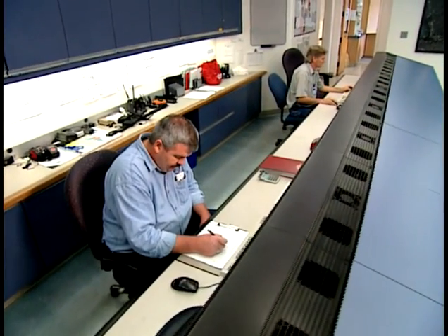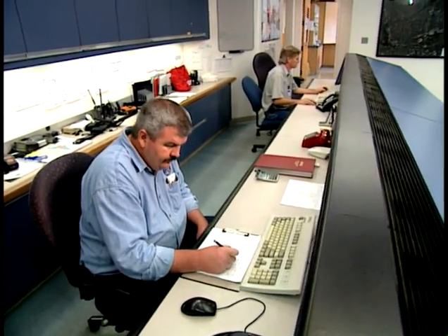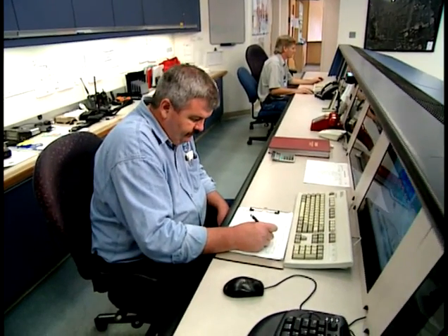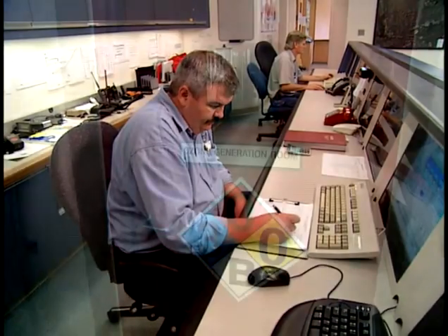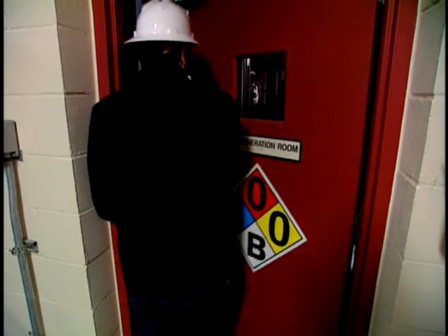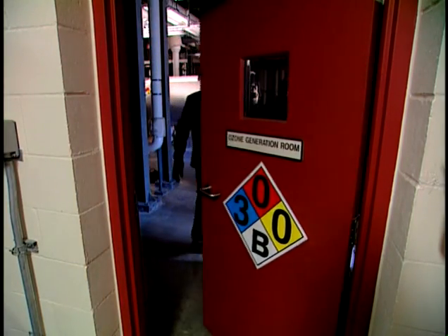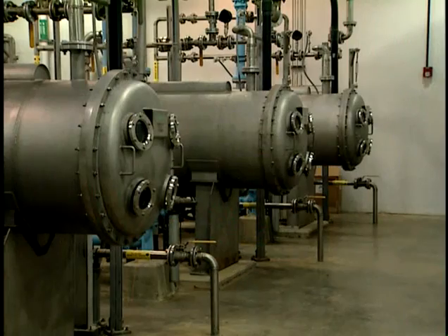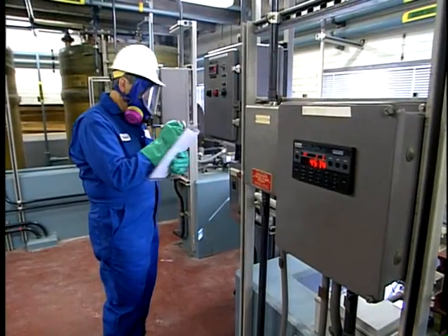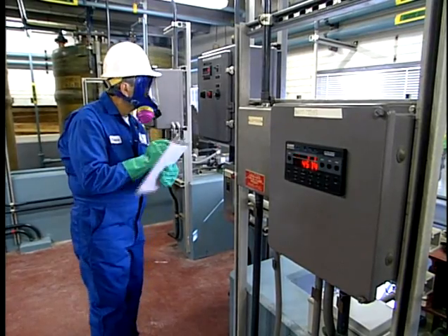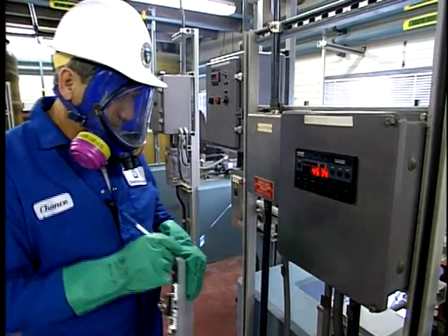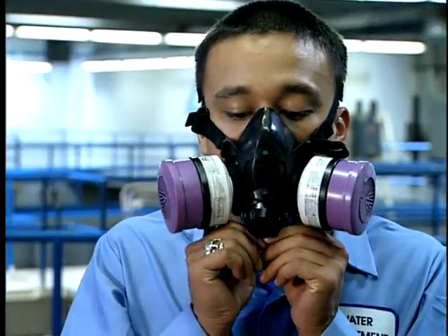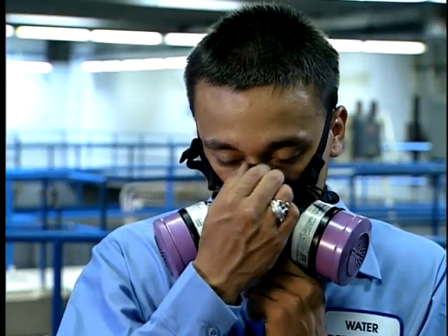Operating limits must be established with consequences of deviation and steps required to correct or avoid deviation. Employees need to be aware of all safety and health considerations of each operation, such as the properties and hazards presented by chemicals used in the process, and precautions necessary to prevent exposure, including engineering and administrative controls and appropriate personal protective equipment.